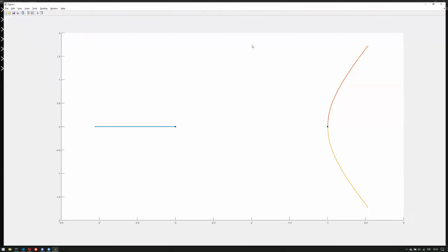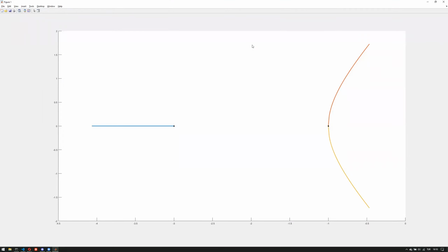There we go. We have recreated the root locus plot. Now, the important thing to remember here is that, even though these look like lines, these are actually points, really finely gridded, and therefore they look like lines. But there's also a theorem that the path of roots is continuous. So if the coefficients do change continuously, the poles will also move continuously on a continuous path. So therefore, these are the lines.